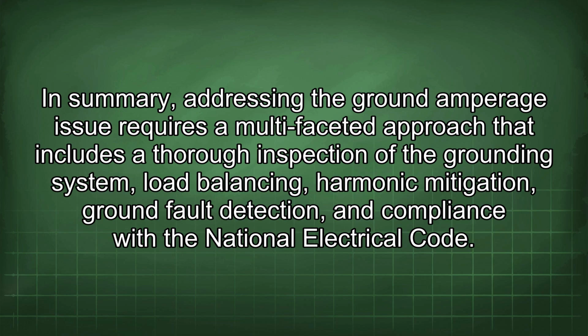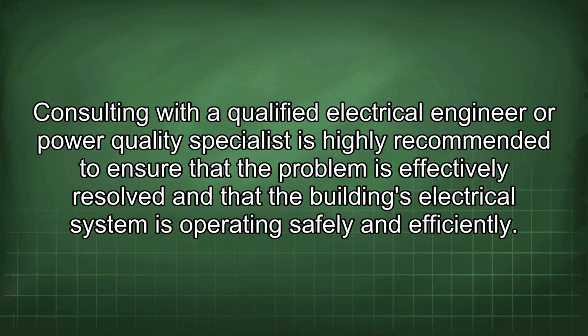In summary, addressing the ground amperage issue requires a multifaceted approach that includes a thorough inspection of the grounding system, load balancing, harmonic mitigation, ground fault detection, and compliance with the National Electrical Code. Consulting with a qualified electrical engineer or power quality specialist is highly recommended to ensure that the problem is effectively resolved and that the building's electrical system is operating safely and efficiently.